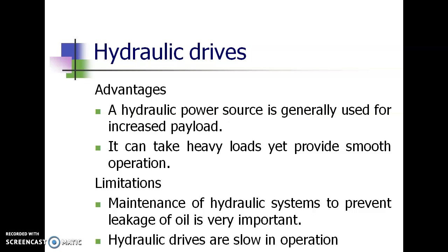And the second one is, because of the inertia of the oil, it cannot be accelerated so quickly. So the hydraulic system is slow in operation, or it is sluggish in operation. The reason is the inertia of the oil.